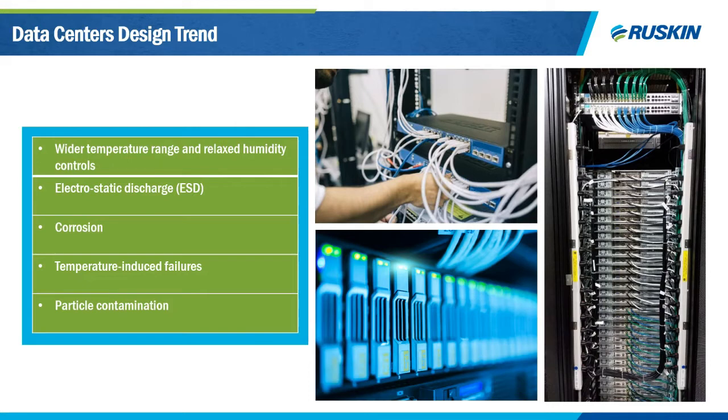If you make the environment too dry, you might run into electrostatic discharge, ESD. And if you make it too cold, you might run into condensation, and that might create corrosion. Also, with 100% outside air, we're bringing a lot of air into that building. We want to make sure that that air is filtered. So keep in mind what classification or class you have from these server manufacturers, and also look at the allowed supply air temperature and relative humidity set point.